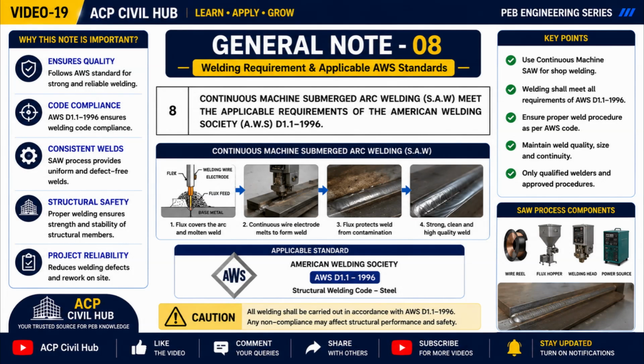During this process, the welding arc remains completely covered by a layer of granular flux, protecting the molten weld from atmospheric contamination. Following the AWS D1.1 standard ensures that welding procedures, welder qualifications, joint preparation, weld quality, and inspection methods meet internationally accepted structural requirements.